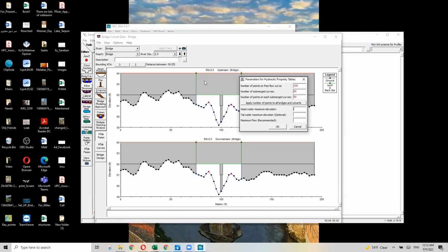When your value is lower and you are using your rating curve in another software, that software tries to extrapolate, and a lot of the time it causes instability. So if I expect my flood stage, for example, for 500 years is 67, I will use even 70 here. That value is never going to be used by my model, but I'm at a safe elevation.